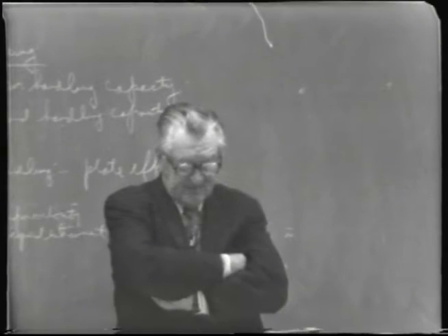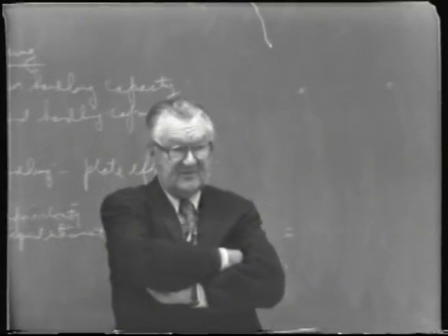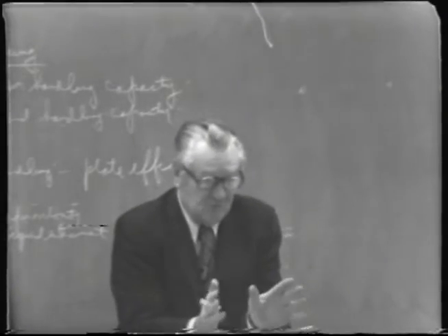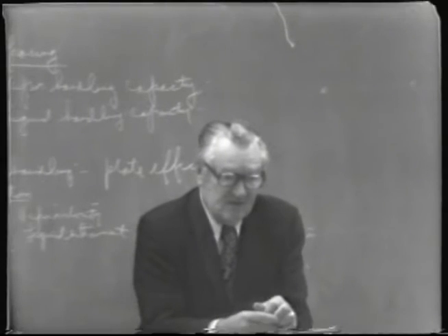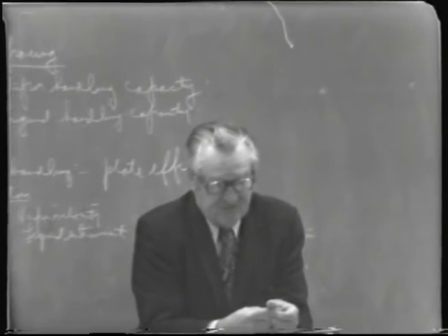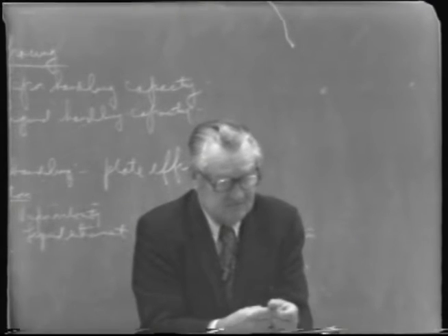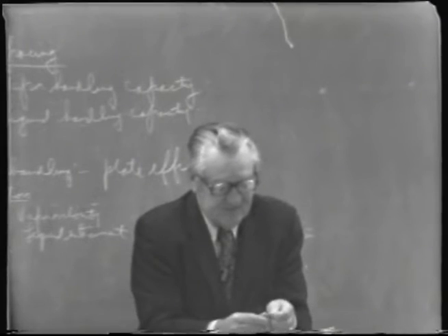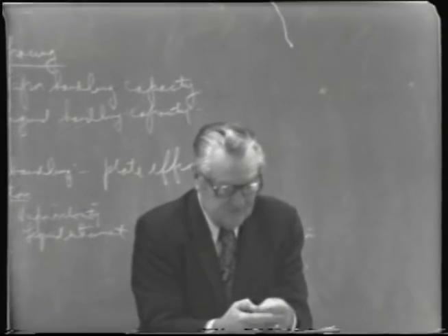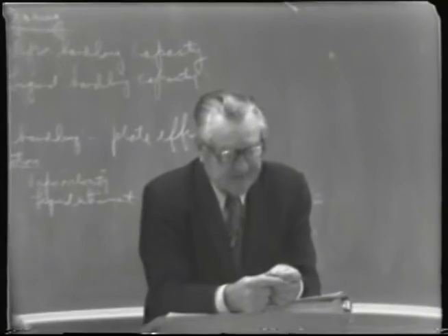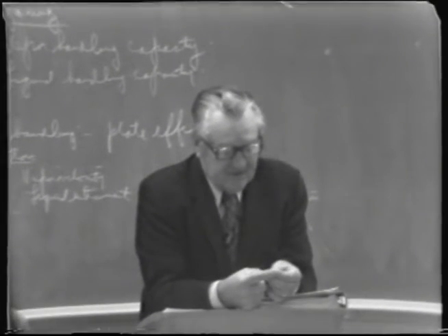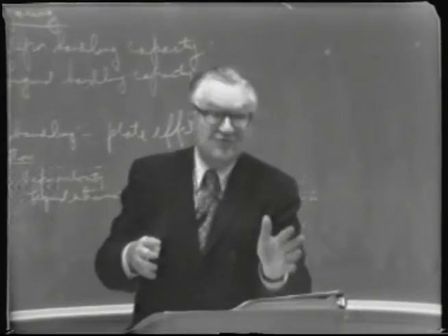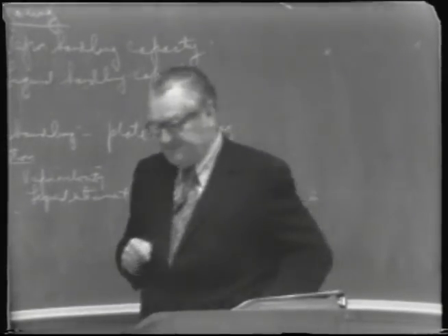And perhaps I'll give you a table at a later period, which I worked out one time, which indicated that from the standpoint of suitable plate efficiency, you ought to have a plate spacing of at least 10 inches for a vapor velocity of about 2 feet per second. So nowadays we recommend that trays be put no closer than 10 inches apart. If you want to go up to 12 or 14 inches of plate spacing, maybe you can get up to 4 feet per second, something of that order of magnitude.